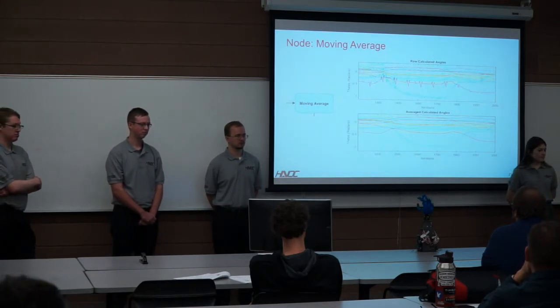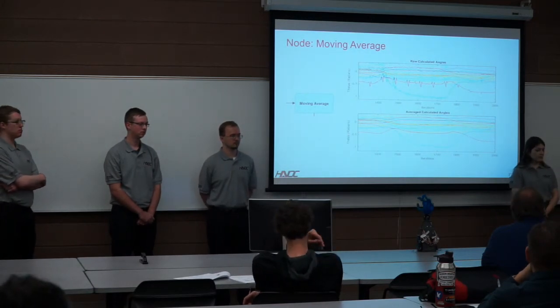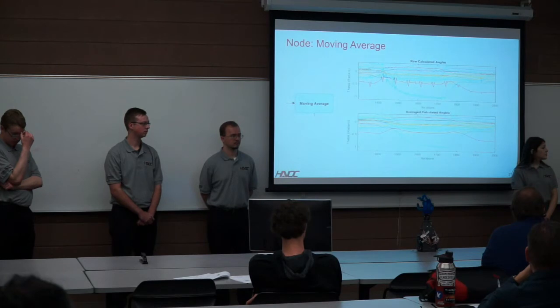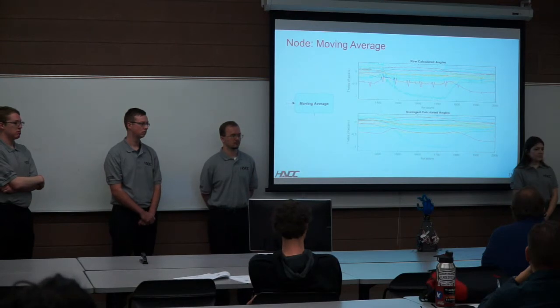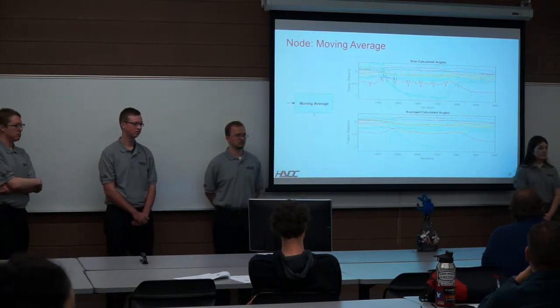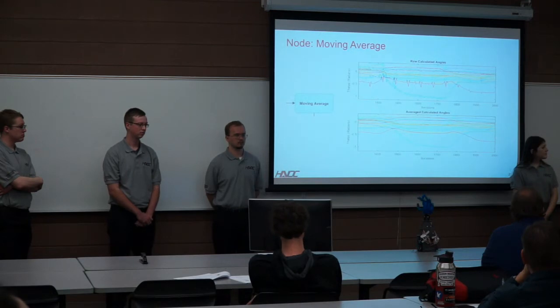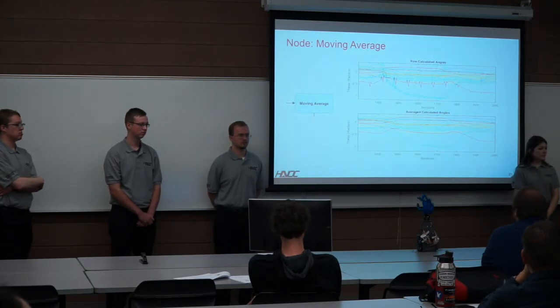I actually saw research where they take rotors and 2 strings and spin the motor, and because the strings wrap around each other, you create a bunch of tension. You can actually actuate things that way. That would have been a really interesting project as well. So mainly, don't go directly to servos. Really rethink how you want to actuate the system.